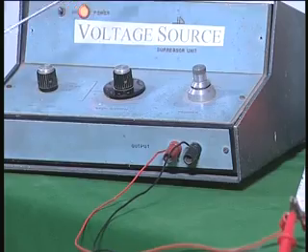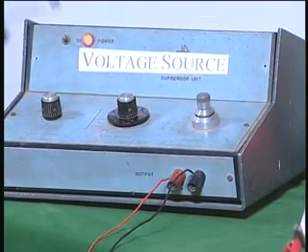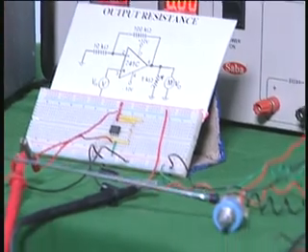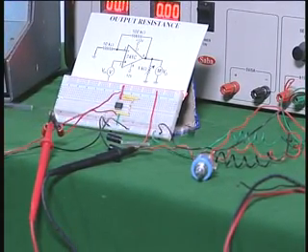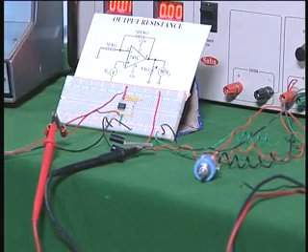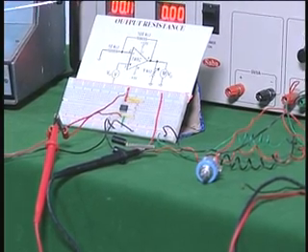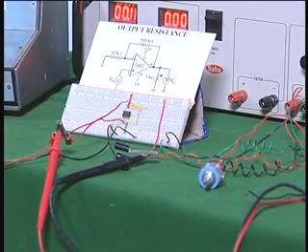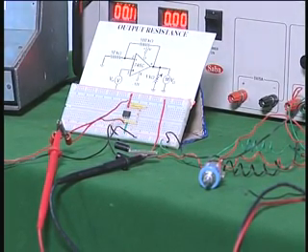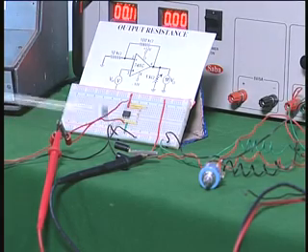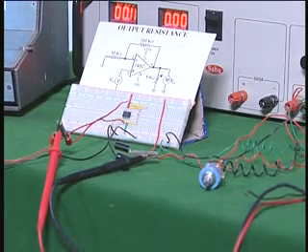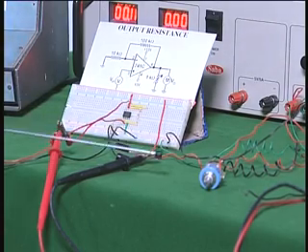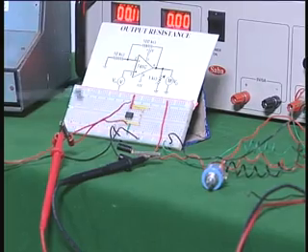Now, without disturbing any of the voltages, I should now connect the variable resistor, which is here. It is actually a 10 turn potentiometer. Usually in our normal potentiometers, if you just rotate by nearly 360 degrees, all the resistance variation would have been made. In this case, you have to rotate 10 times the spindle to make the variation possible for the whole range, and therefore you can do it in much smaller increments of resistance. That is why I am using it.